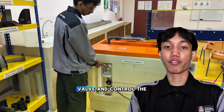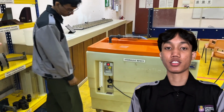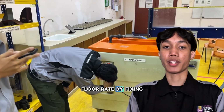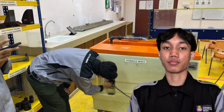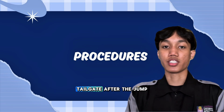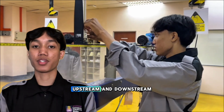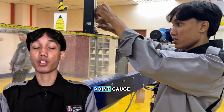Next, we open the valve and control the flow of water. Then we close the dump valve and we must measure the flow rate by fixing the volume and setting the time. Then we close the tailgate. After the jump has stabilized, we measure the upstream and downstream water depth using the point gauge.